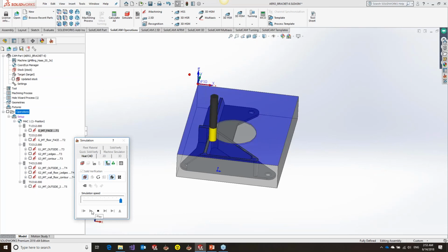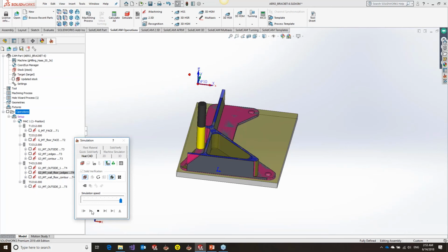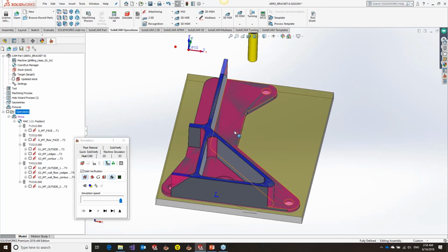So the first tool does the roughing of the top, finishes the top, and then the roughing tool is now going and doing all the roughing for all the pockets before it goes on to doing the finishing. Okay, so really nice. You can reorder the operations. Of course, I think anybody should have assumed we should do this, but this is something that maybe people think would not be an option in multi-tool since you're defining all the tools in one operation.